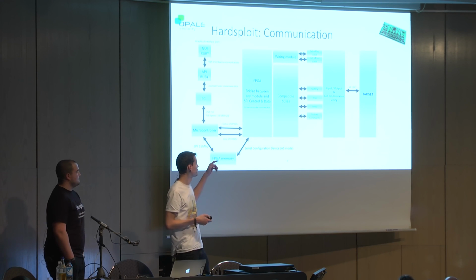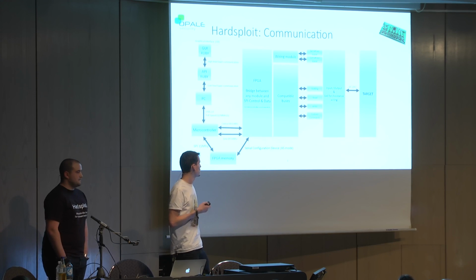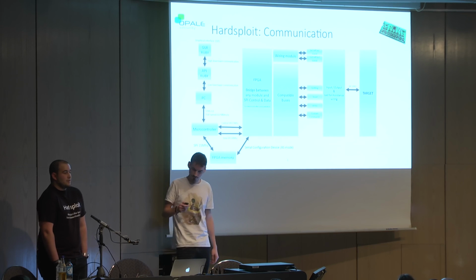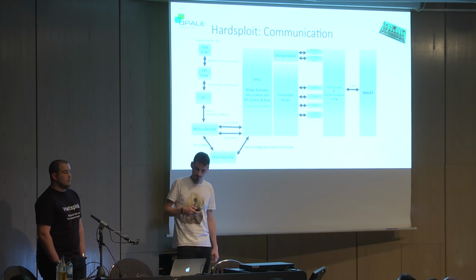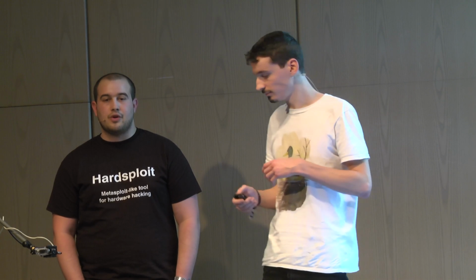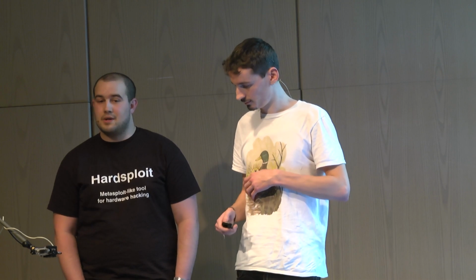You can see a quick list of possible interactions, like sniffing, reading, writing, and executing custom commands. And if you create a custom module for the FPGA, you can load another one and interact or create whatever you want. If you know VHDL, you will be able to create your own Hardsploit module to work with a specific bus, for a custom protocol, for example.